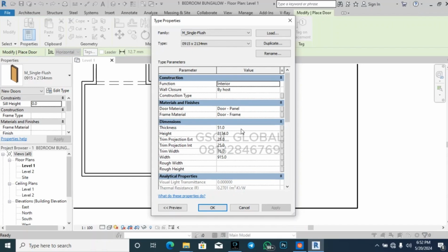Your kitchen also goes with your room door, it depends on how big the space is. If your kitchen is like a toilet, you can still go with 750 mm by 2100 mm. But if your kitchen is big enough, then you have to create an access door that is also at least 900 mm by 2100 mm.